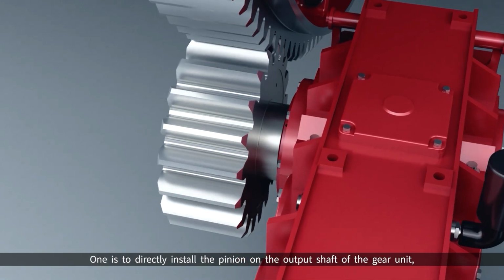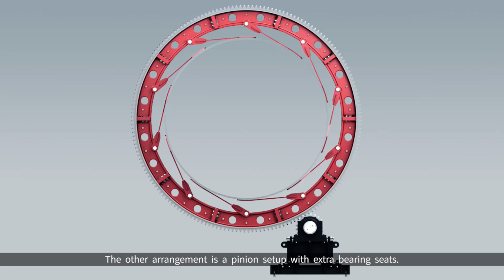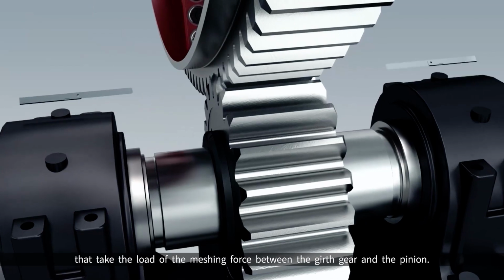One is to directly install the pinion on the output shaft of the gear unit. The other arrangement is a pinion setup with extra bearing seats. The pinion shaft is supported by two independent bearing seats that take the load of the meshing force between the girth gear and the pinion.